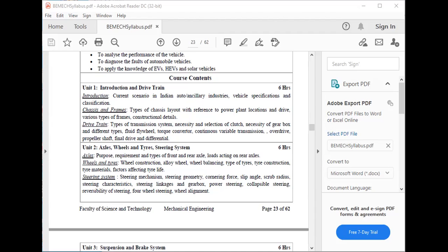If we see here, these are the torsional springs and this is the cover. Torsional springs can be spring or rubber, and dampen power impulses from the crankshaft. For damping purpose it is used. Torsional springs have pins to limit the amount of twist. Springs try to keep it centered between the pins. Then friction disc cushion springs, wound metal between clutch holes, dampen the clutch engagement.